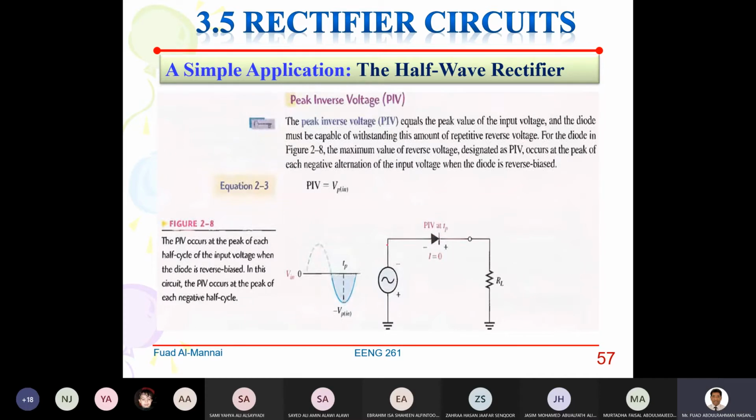So the manufacturer will give you a certain PIV figure, and then you have to calculate your PIV based on the value of the input voltage. So if your input voltage peak value is, say, 20 volt peak, then you look at the PIV of the manufacturer and say, oh well, I'm way less than what the manufacturer quotes in the data sheet. Therefore I'm safe.